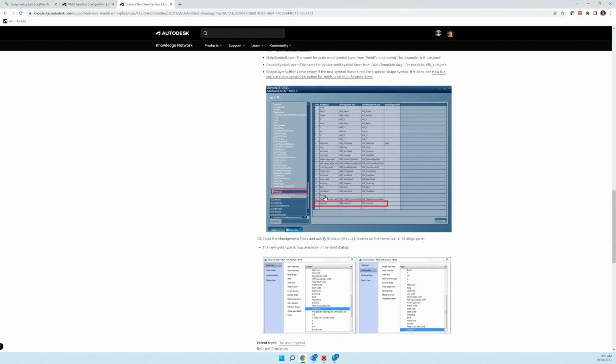So all I've done there is move those 2 welds, because I had line 21 for the top weld and line 22 for the bottom weld. I've moved both those two lines from that table further down, and hey presto, problem went away.